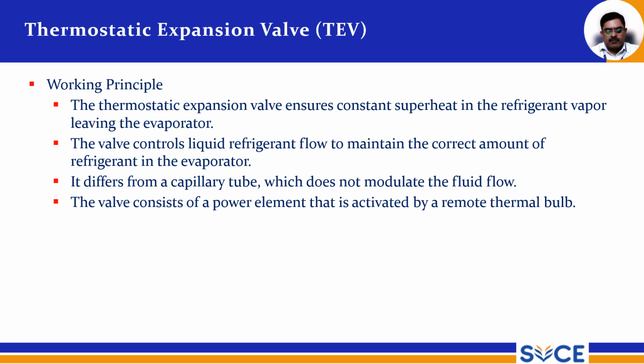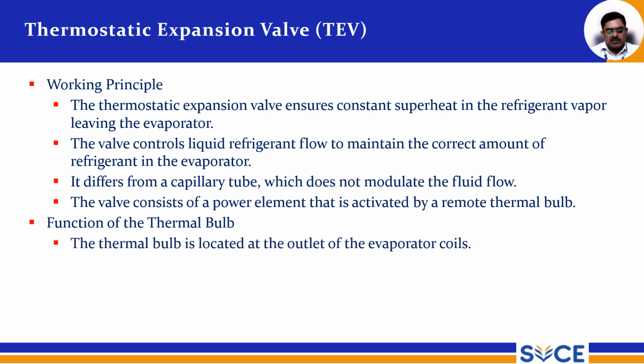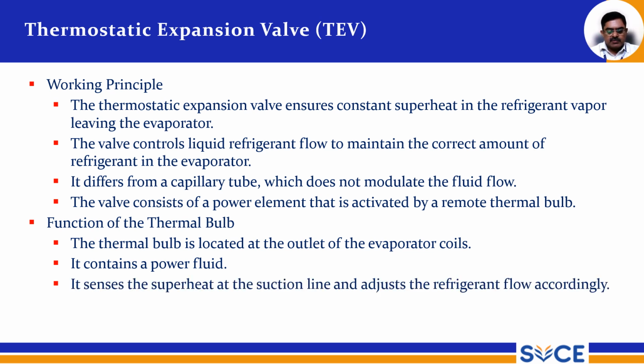The valve consists of a power element that is activated by a remote thermal bulb. The thermal bulb is located at the outlet of the evaporator coils. It contains a power fluid, and it senses the superheat at the suction line and adjusts the refrigerant flow.